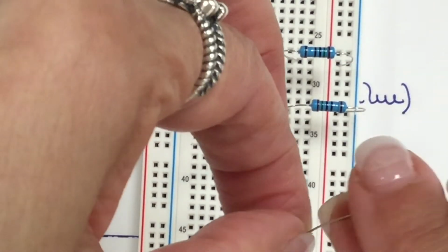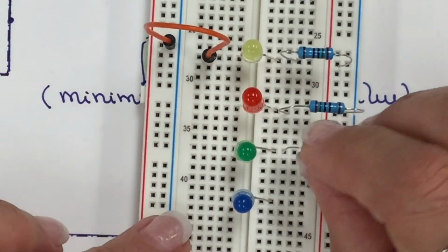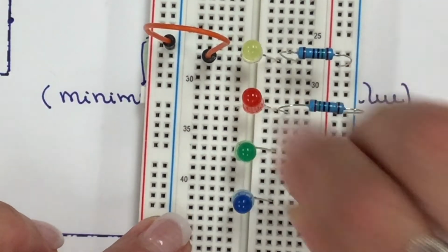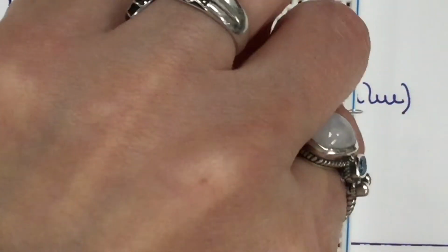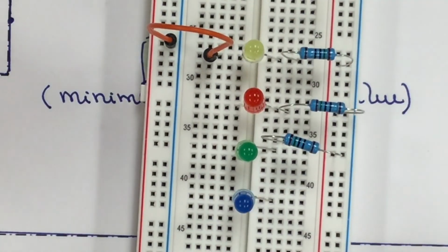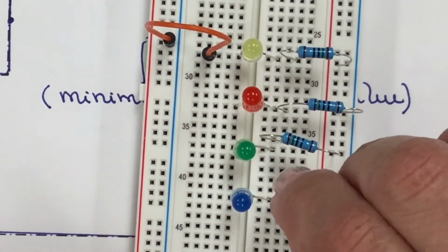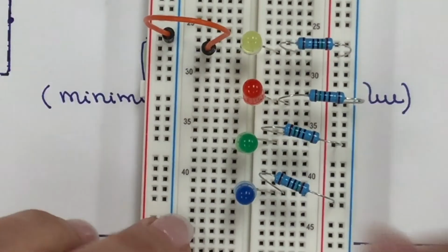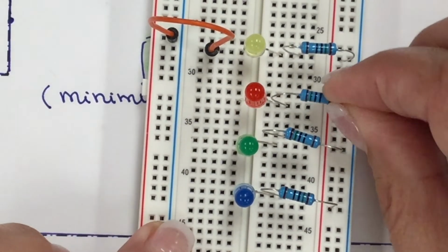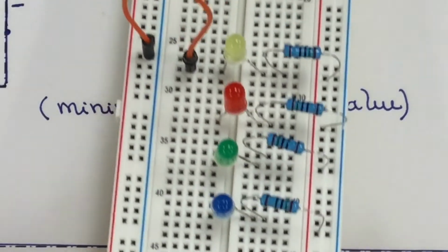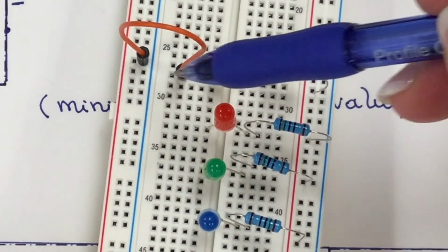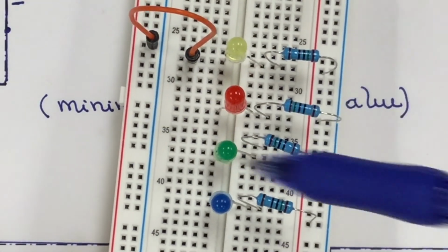And likewise, the next LED here to the positive. And the last one here and positive. So this is how it should look. So it's kind of a repetition of the first circuit because they are in parallel.